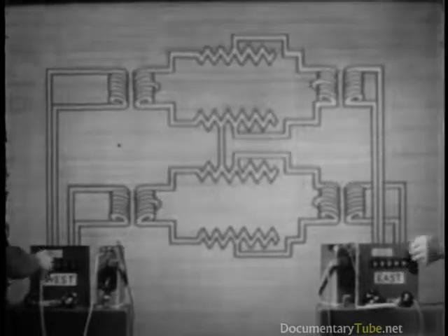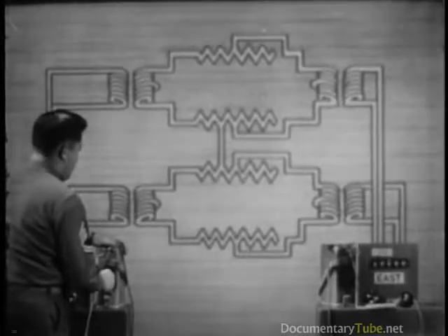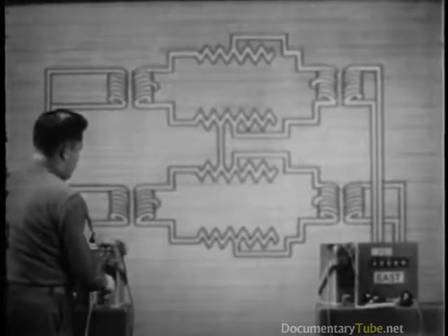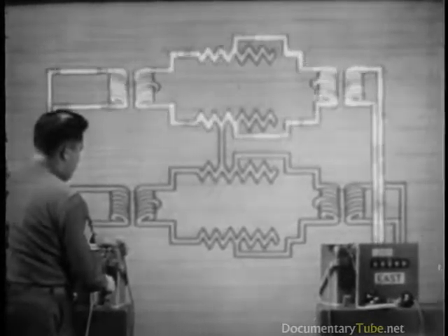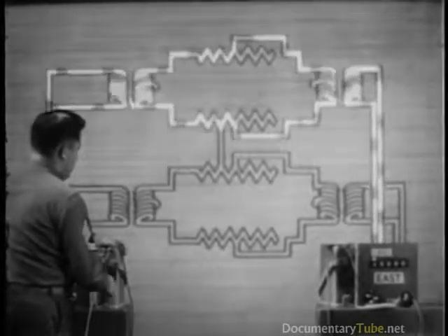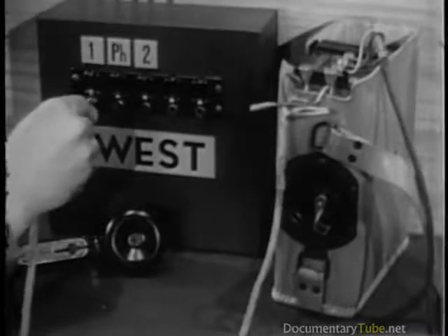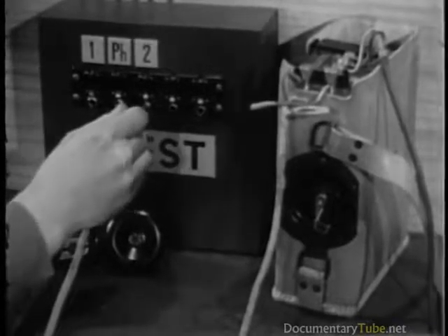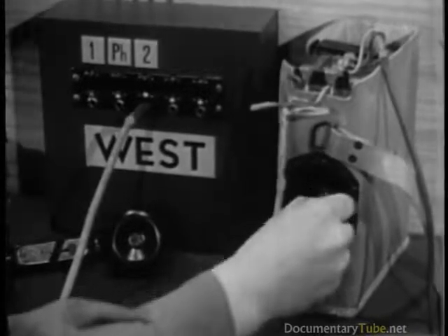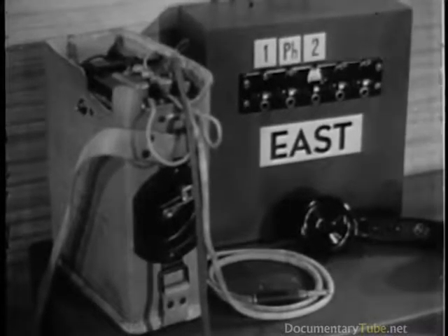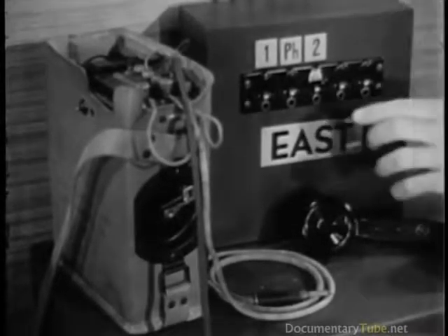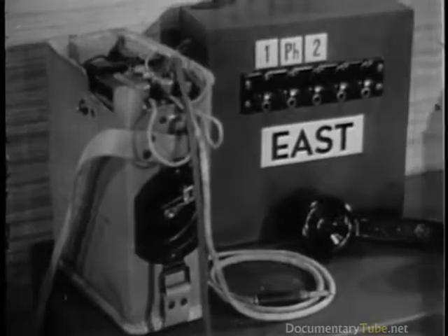If we cut out the phantom connections at both ends, the 2 side circuits can be used. Actually, we no longer have a phantom group. What we do have is 2 metallic circuits accidentally crossed, and we won't get any more interference between them than is usually caused by this condition.